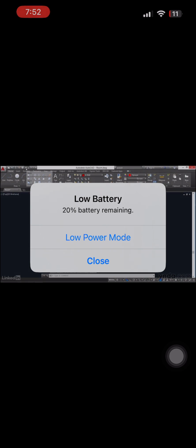Let's undo. In the case of this room, I would like to offset this line over a distance equal to the width of the wall. So I could either measure the wall with the measure tool here and learn the distance, or I could click 2 points and have AutoCAD measure it for me within the offset command. Let's take the latter approach. Click Offset.